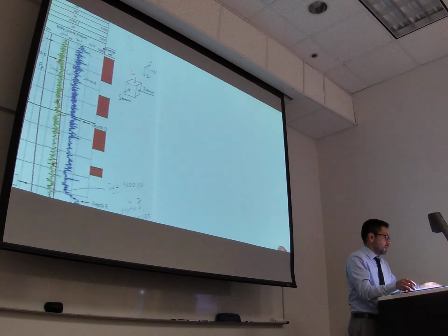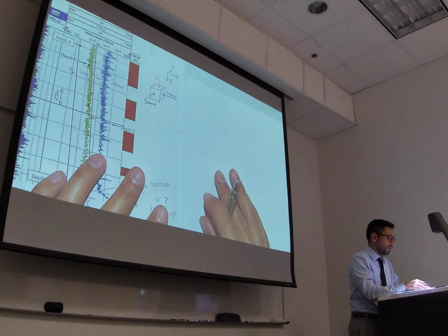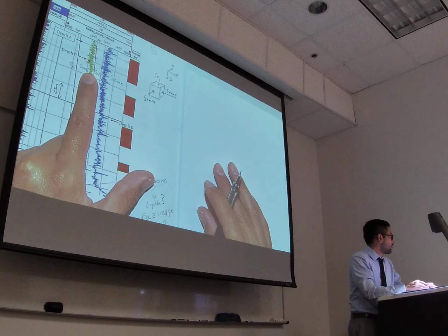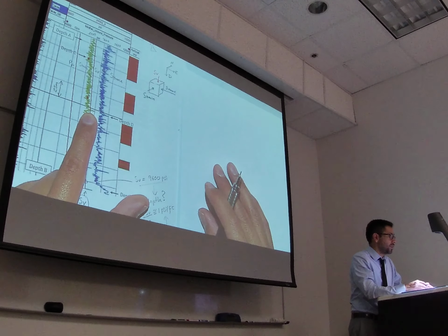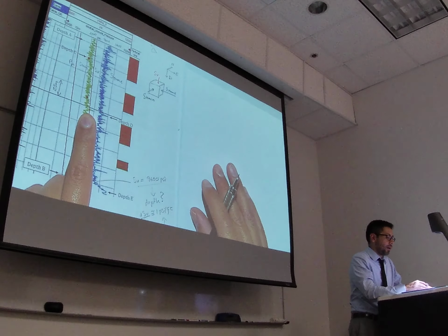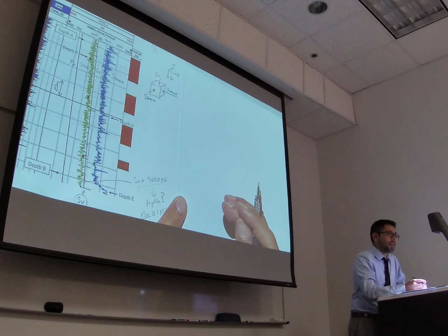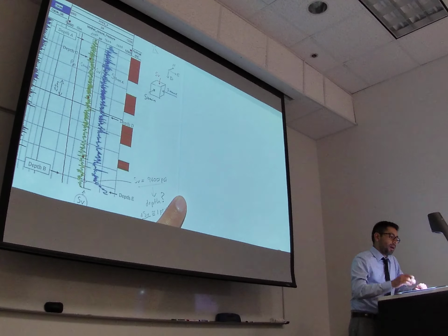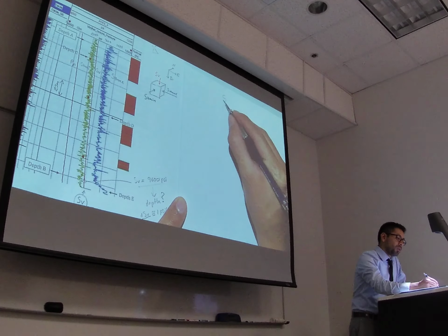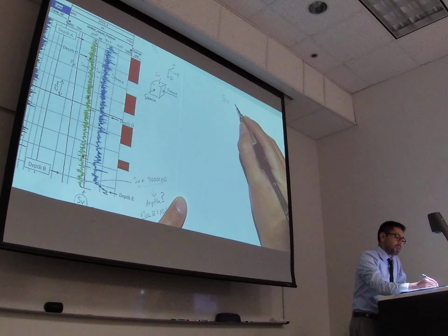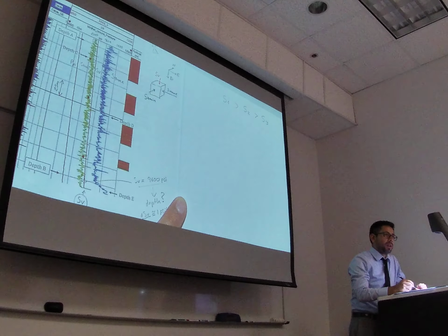So we were saying before that there are places in which the horizontal stress may be the minimum principal stress, but there are some other places like over here where it is not. So those variations are very important, and there is a classification for that to tell how those may be ordered in a particular place. So in a place where the maximum principal stress is S1, larger than the intermediate stress and larger than the minimum principal stress,